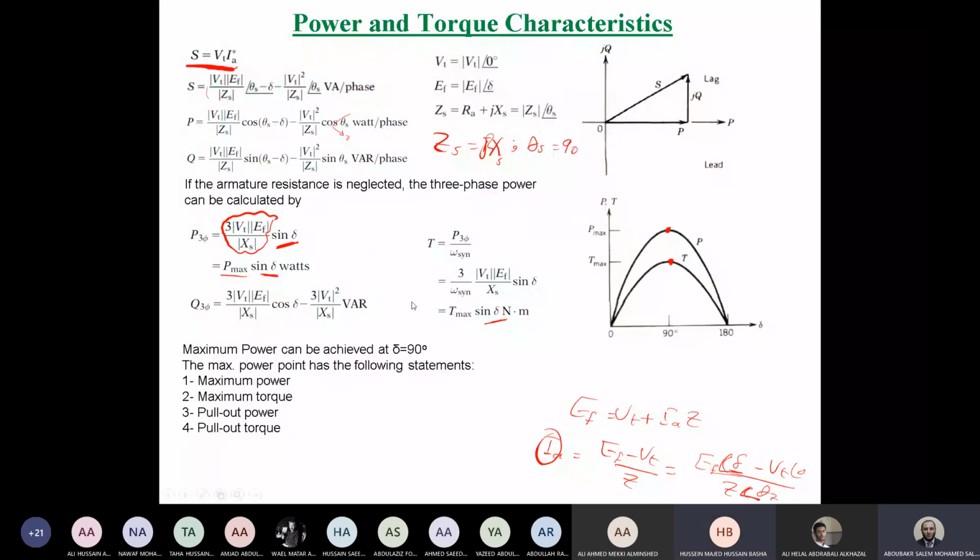Doctor, since we don't want to reach the maximum value, why don't we make it like the circuit breaker, so that as soon as you reach the maximum it trips? Now it's already used, but not at maximum, because if you reach the maximum the device will be damaged before the breaker disconnects. So you should design it to be lower than maximum.